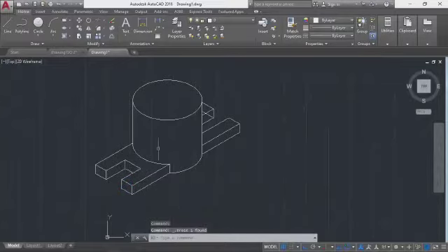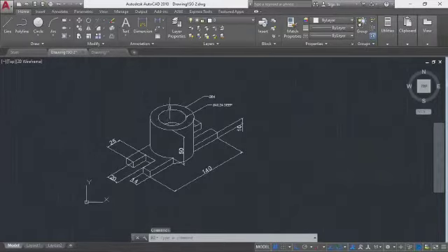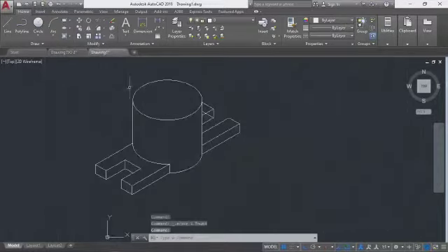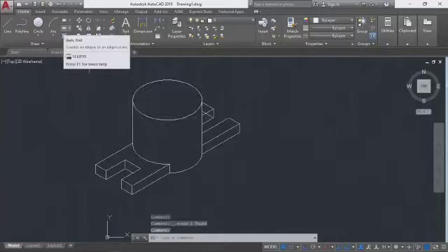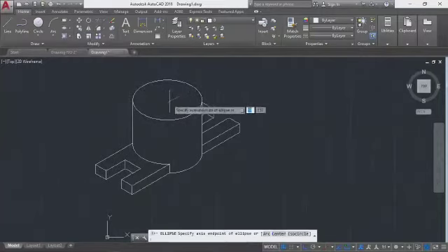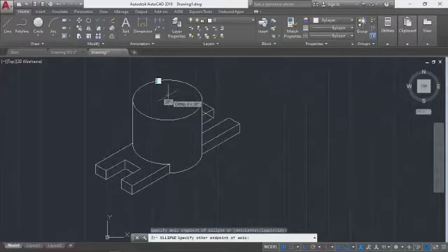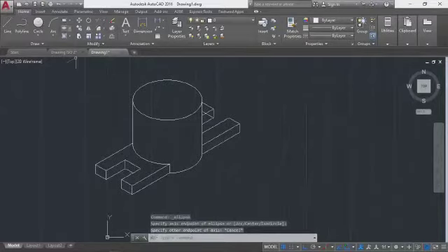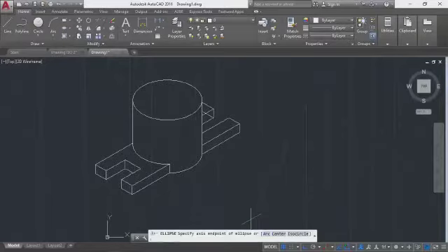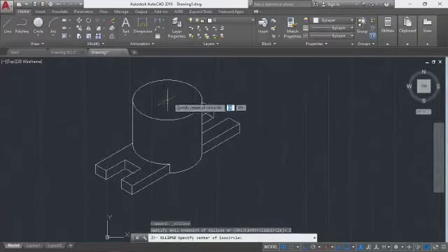So what do you do to this now? You have to draw this inner circle. You can see there is another circle here, which is an ellipse of 40 diameter, and of 24 deep. You come over here and you click on ellipse axis and you pick the center of this point. This is the center. You pick. You click on ellipse. Don't forget isocircle, sometimes we forget. Then you come to this point and you pick the center point.